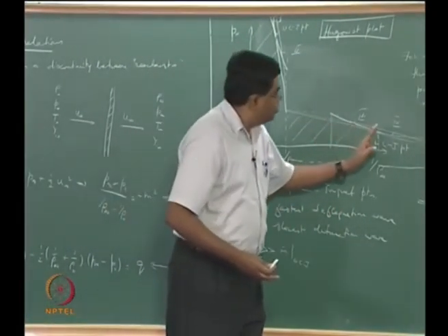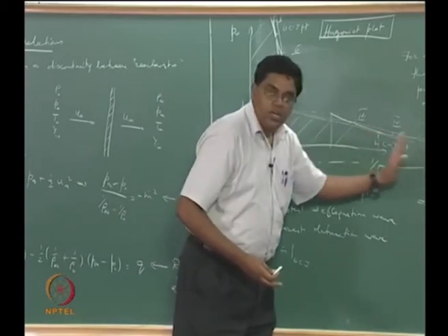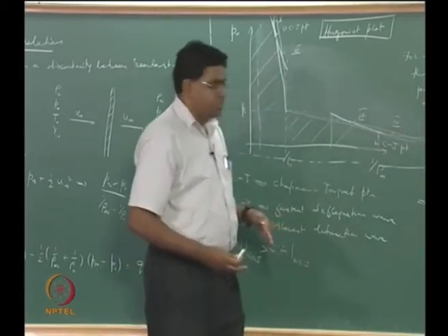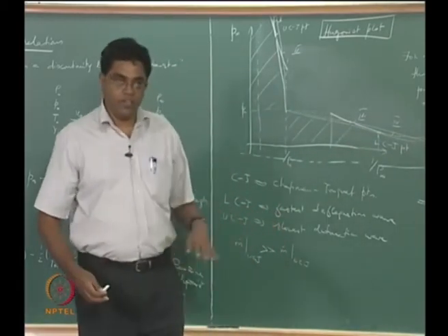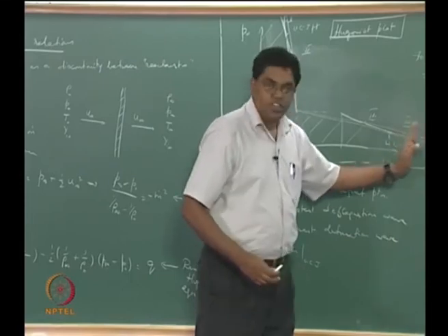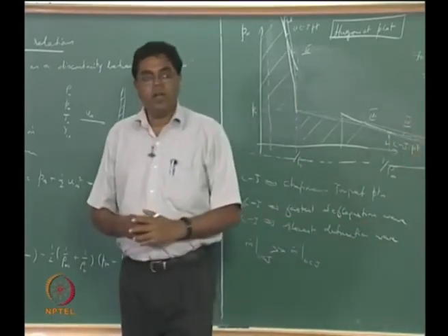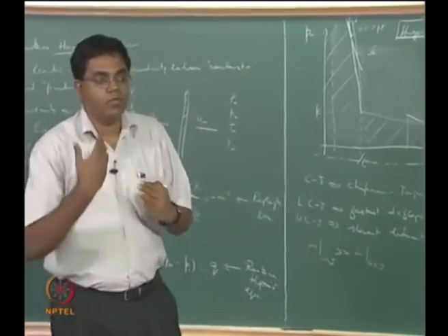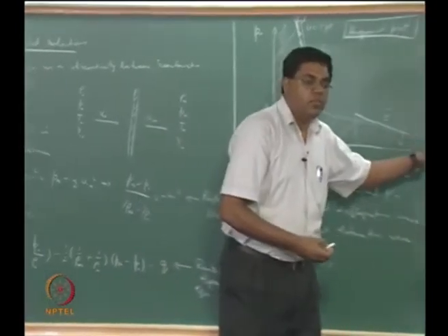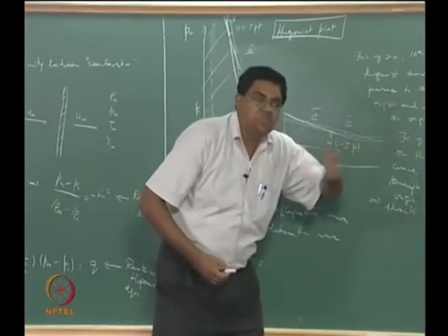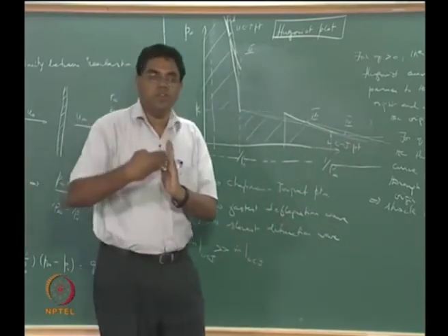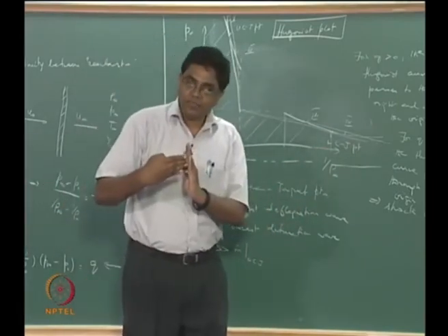But when you now go past the LCJ over here to the strong deflagration, what that means is you are now having a very large amount of expansion that is going on, correspondingly there must be a very significant amount of acceleration that goes on, to the extent that we end up finding that the products actually have supersonic speeds by the time they are getting past this wave, although they started out with subsonic conditions for the reactants.